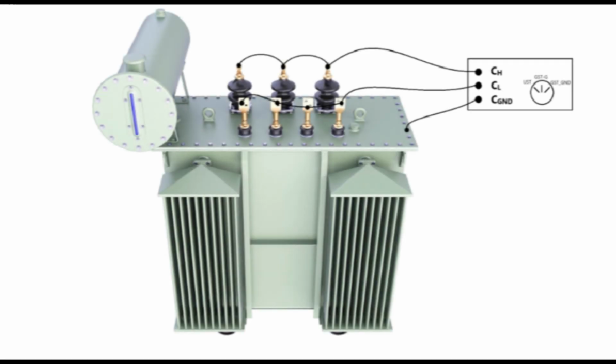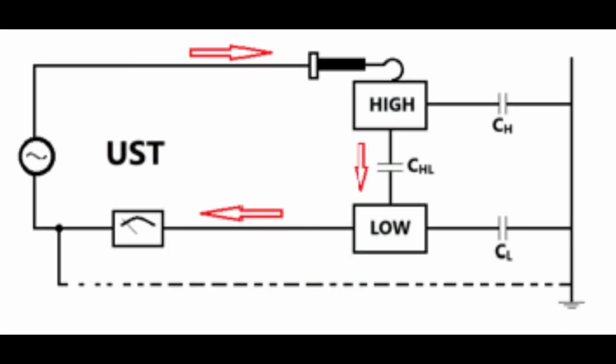The dissipation factor, DF, test, also known as the tan delta test, is used to assess the insulation quality of a transformer. To measure dissipation factor, first the high voltage winding should be shorted and the same for low voltage windings. Then apply AC voltage to high voltage windings, measure the dissipation factor, tan delta, and analyze the ratio of resistive to reactive components. Modes of test in dissipation factor devices.